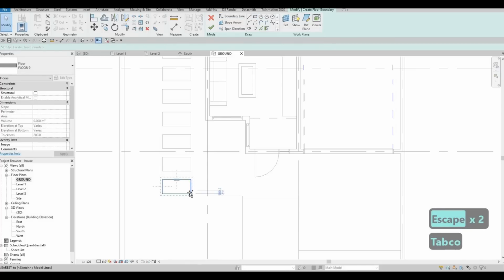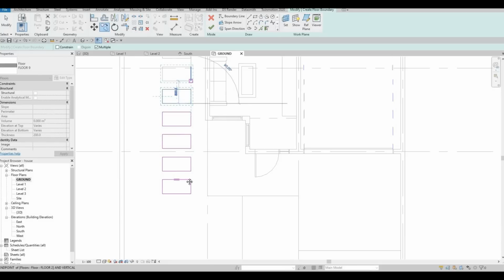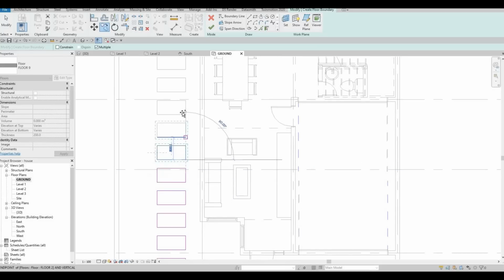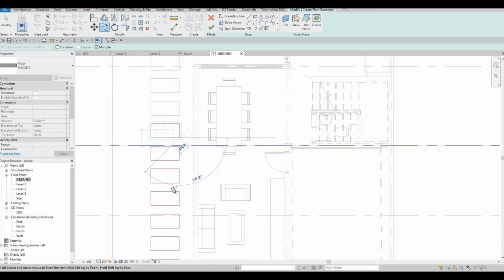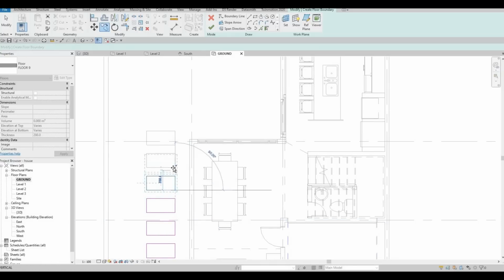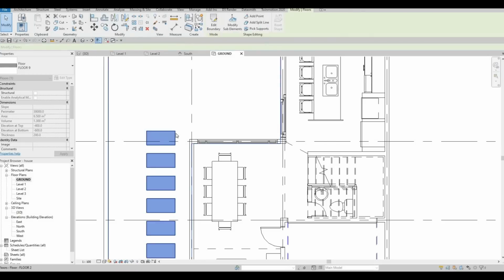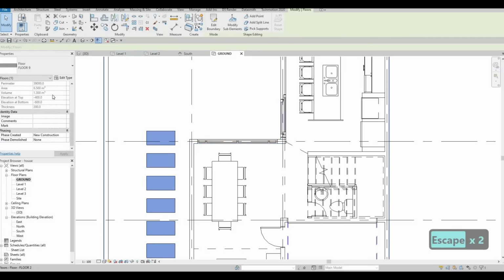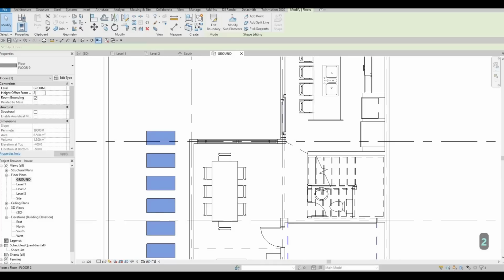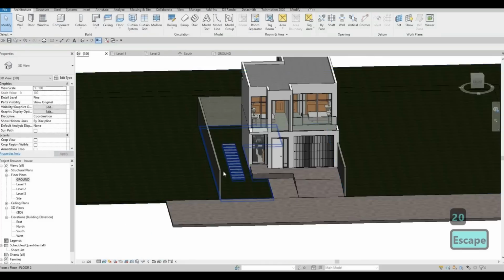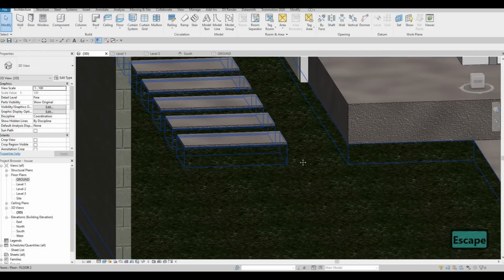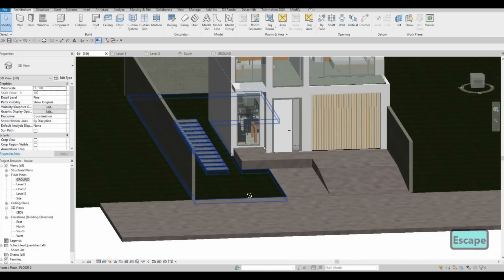And then copy it on the edge. And then click finish. Select that. Constraint, I want it to be offset on 20. I think that's good enough for that part right there.